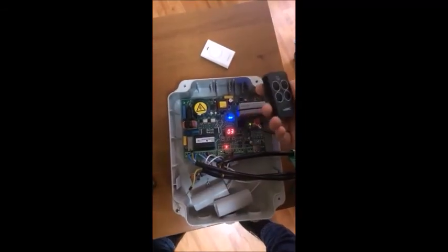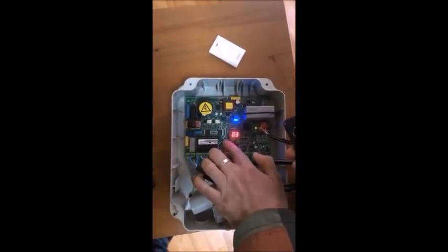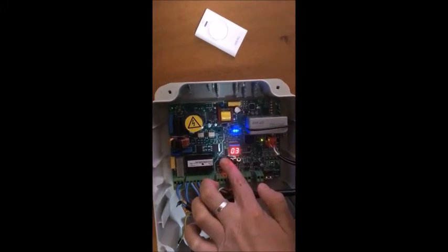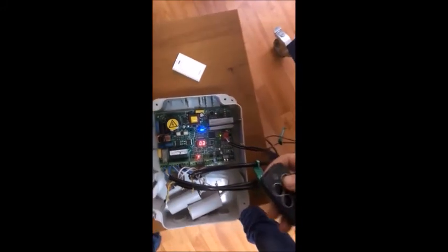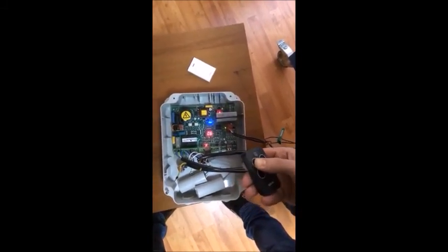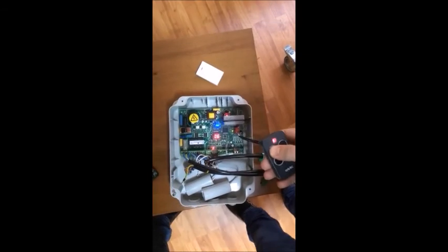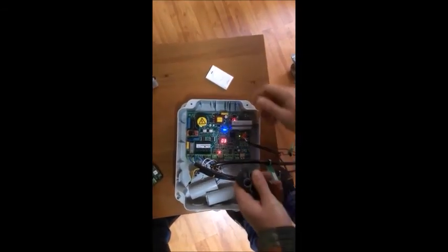To add an RC remote control to the open A function on the E045, once again press and hold the plus button for about 5 seconds until you see the red radio 1 LED start to flash. Then all you do is simply press and hold the desired button on the RC transmitter. The red LED goes solid, indicating that the button has been learnt, and your button is now available to operate the gate.